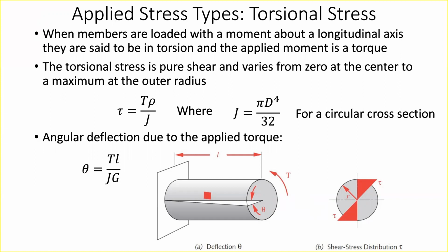The distinction is a little confusing at first. A normal stress is, if I take a cross section of my object, the load perpendicular to that cross section. The shear loads, in contrast, are actually in the plane. So if I take that cross section, the shear loads are all aligned where my finger is pointing, in the plane of the cross section themselves. This diagram shows the plane of the rod, and these values of tau are what we refer to as a shear stress. It's very similar to the normal stress: you just have a different direction of the load, and it's still a pressure at the end of the day.